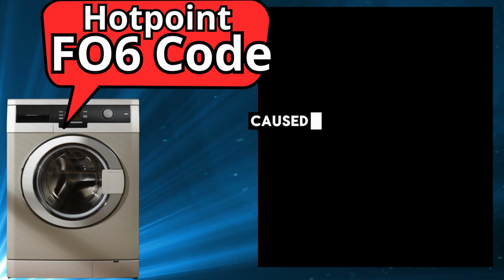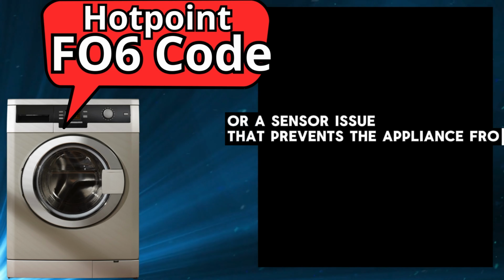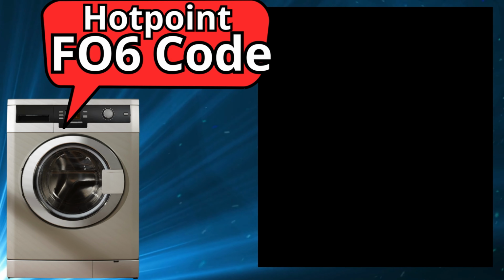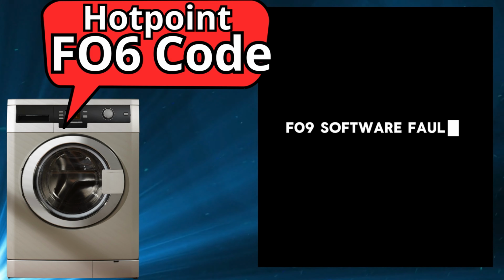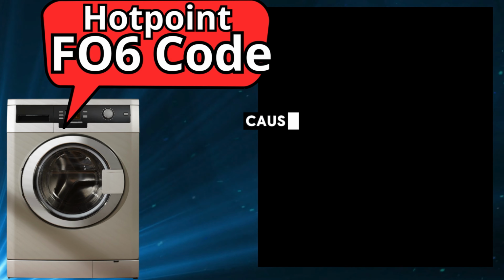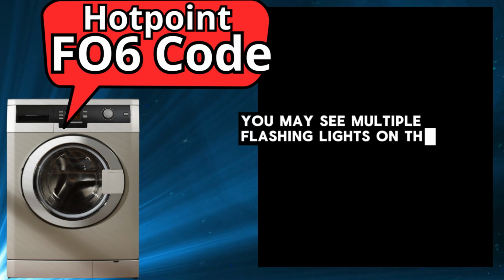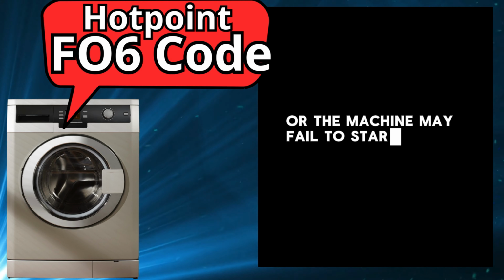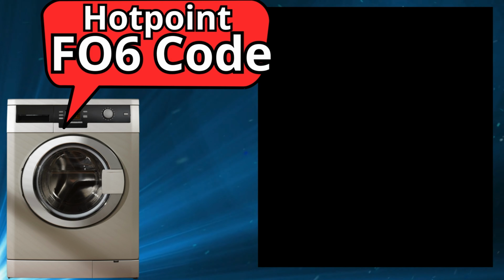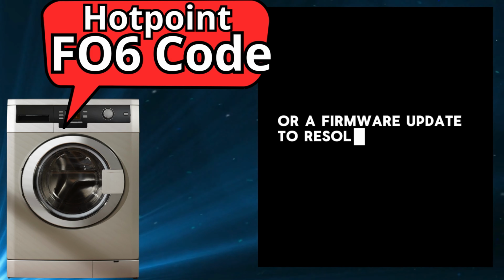This is usually caused by a malfunctioning heating element or a sensor issue that prevents the appliance from reaching the required temperature. F09, software fault. An F09 error is related to a software malfunction, causing the washing machine to become unresponsive. You may see multiple flashing lights on the display, or the machine may fail to start or allow program selection. This often requires a hard reset or a firmware update to resolve.